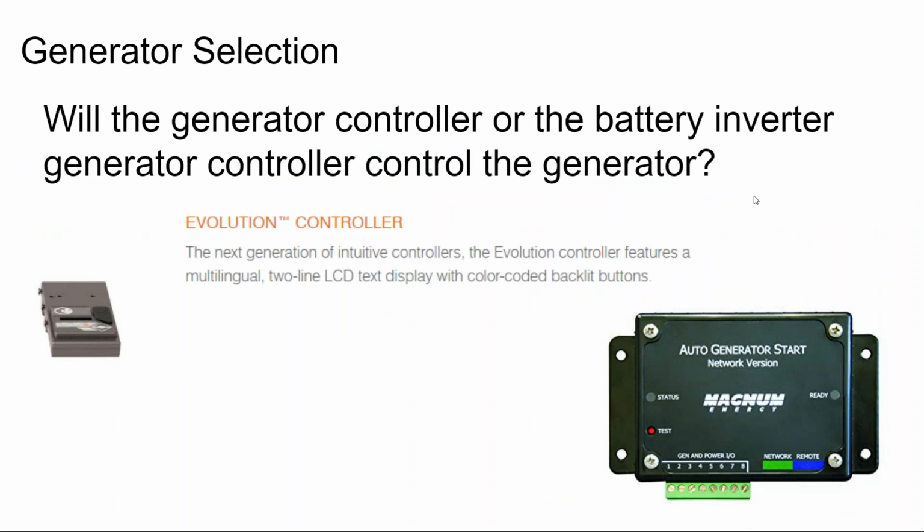First, most of your battery inverters will have a generator control board to trigger an auto start. And so you don't need a generator that has its own function to monitor the battery voltage and, when it gets low, start up, because it would be better to have the inverter, which is the brains of the system, drive the generator rather than the generator drive itself.